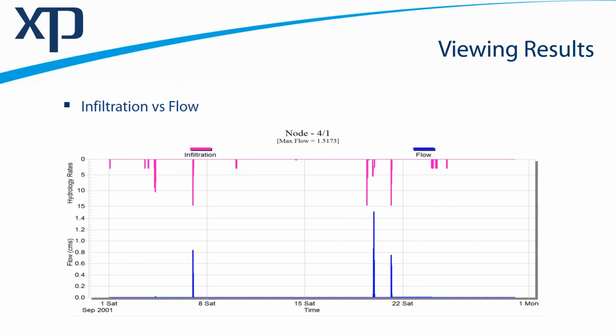When we look at long duration modelling, infiltration is a very, very important parameter. We can lose large sums of water through infiltration. This shows blue at the bottom. And the interesting one that I always like looking at on this particular data set is that this second storm here is the smaller storm with the peaky storm before it, generating almost no runoff because it's picked up in losses. The catchment was dry, had a dry period for certainly a few days beforehand, but it's that second storm that followed the first one that actually creates the big discharge rates.